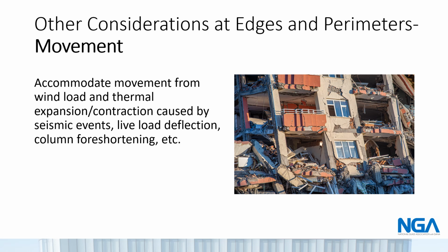Any continuity of the thermal line in the glazing system to the surrounding thermal insulation should be able to handle the potential amount of movement at the location in question. There should be no degradation of the thermal line continuity or its insulating properties long term. For example, on a typical curtain wall, a plus or minus 3/4 inch perimeter joint around the frame is normally utilized. This allows for building movement which may include actual structure movement, glazing system deflections, thermal expansion and contraction, variation in surround opening tolerances, and sealant movement capacity.